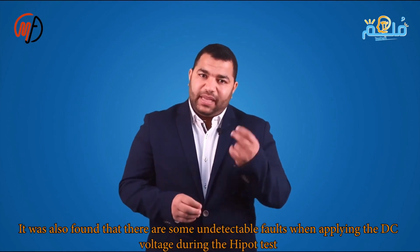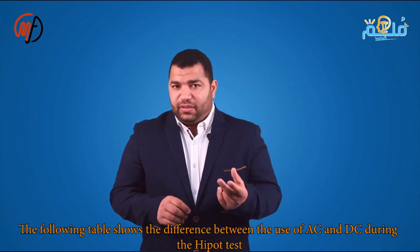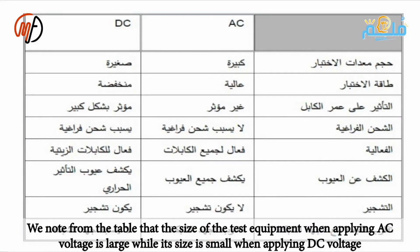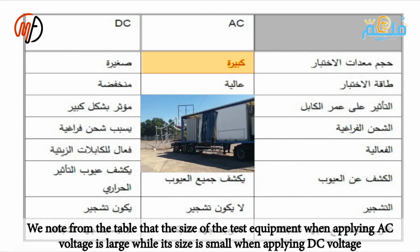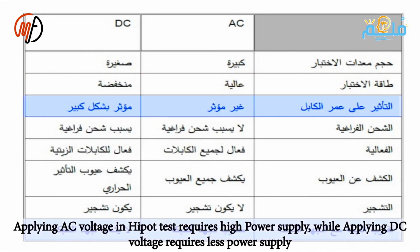The table compares AC and DC in hypot tests. As shown, AC equipment is large, DC is small. AC uses high energy, DC uses less. AC does not affect lifespan as it simulates network voltages. DC impacts lifespan due to space charging, leading to treeing. AC reveals most defects. DC only thermal.